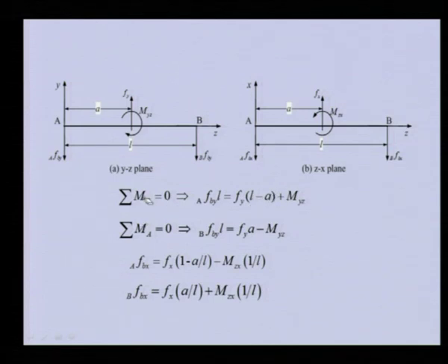Similarly, in the same diagram we can take the moment about point A. Then we get this particular bearing force, whose moment arm is L, and these are the disc reaction forces. Their sign is opposite because they are now producing a moment in the opposite direction. You can see Fy is acting in the counterclockwise direction, Myz is acting in the clockwise direction, so its sign is negative.